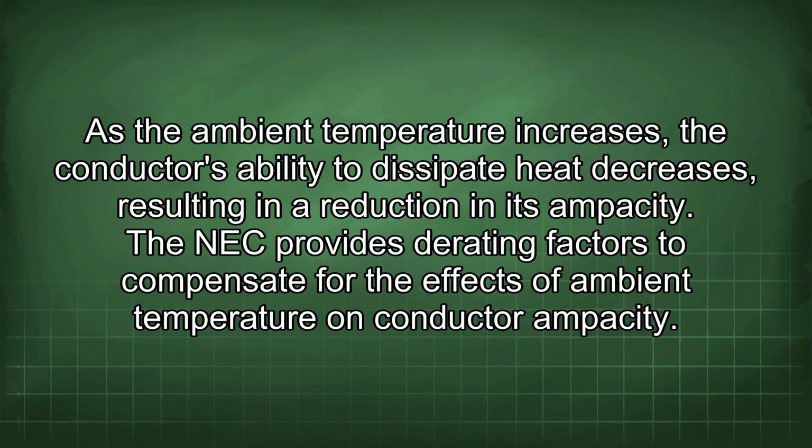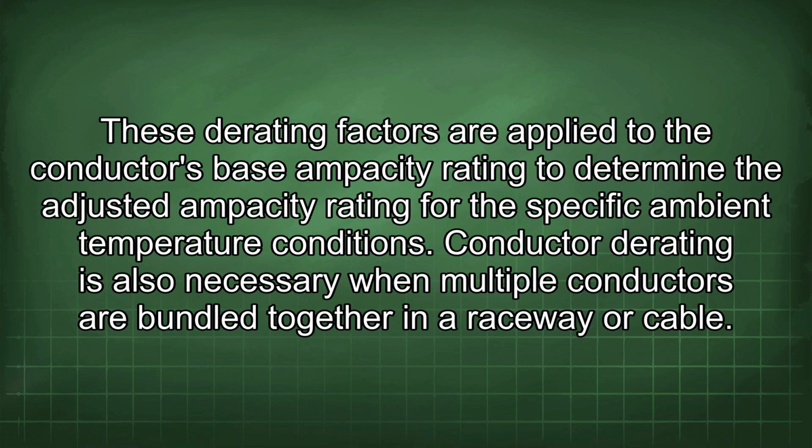The NEC provides rating factors to compensate for the effects of ambient temperature on conductor ampacity. These rating factors are applied to the conductor's base ampacity rating to determine the adjusted ampacity rating for the specific ambient temperature conditions. Conductor rating is also necessary when multiple conductors are bundled together in a raceway or cable.